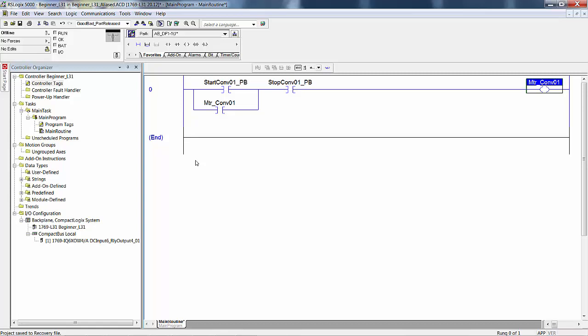Personally, I would use many smaller controllers instead of one big one, mainly because if something goes down in one area, you don't have to shut down all 7 areas because you only have one controller. With 7 controllers, you just shut down the area where you have the problem. Okay, moving ahead.